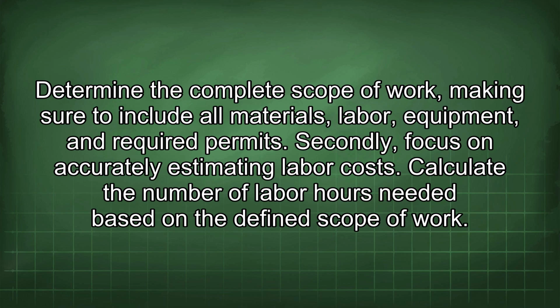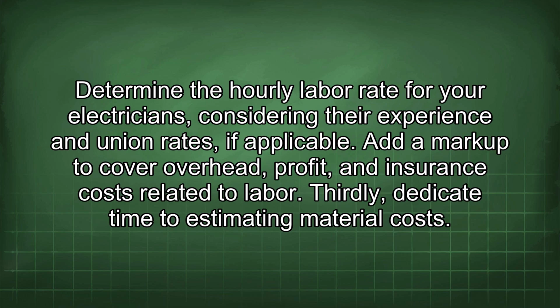Secondly, focus on accurately estimating labor costs. Calculate the number of labor hours needed based on the defined scope of work. Determine the hourly labor rate for your electricians, considering their experience and union rates, if applicable. Add a markup to cover overhead, profit, and insurance costs related to labor.